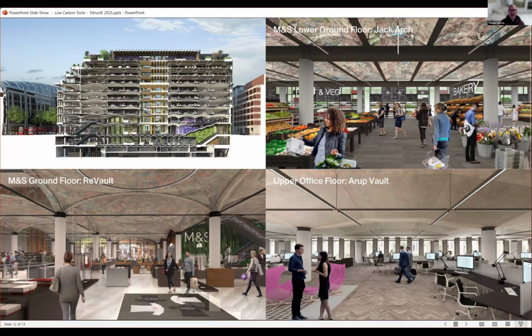And we've come up with a scheme which got planning permission last year, thanks to my colleague Kerry Greaves, of reusing all the existing material from the 4 existing buildings to build the lowest buildings, and then putting 3 more stories on top using the vault system I showed you before. Now, the technique here is not to design what you want from a clean sheet of paper, but instead to start with what you have available in terms of materials, and then design a structural system that reuses those materials that you have available.